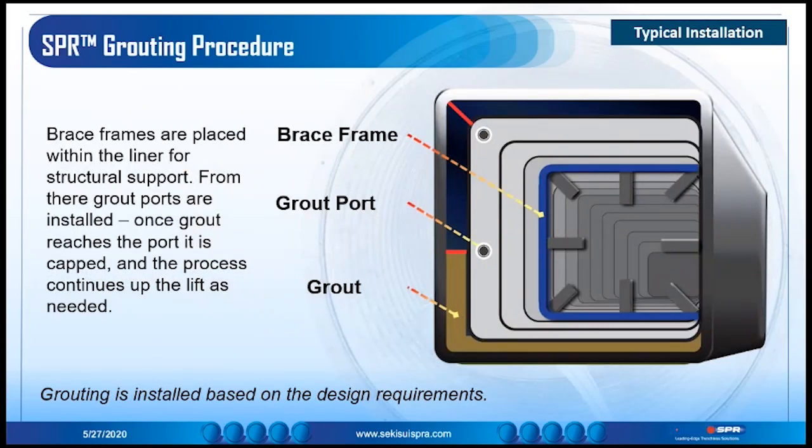After selection and strength of the grout is determined, we will then work with the installer to select the best procedure for installing the grout in the annular space. After bulkheads are placed at the end of each liner in the rehabilitated segment, we will decide about the type of bracing system needed to support the liner and prevent it from floating during grouting.